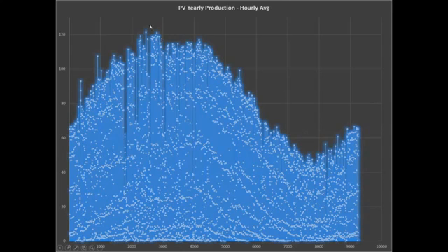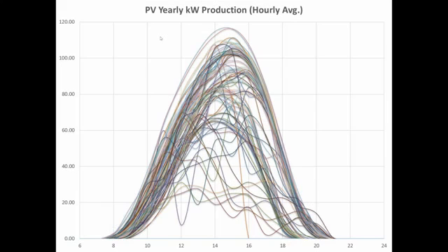Now, if you remember in the initial estimates, we sized the system at 180 kilowatts. We applied an NREL factor of 0.75, as I had mentioned, and we expected the output to be about 133 kilowatts peak summer. So we did not really achieve 133 kilowatts, but we did achieve about 125 or so. So we were not that far away from what the NREL factor estimated, and this is actual production data showing us.